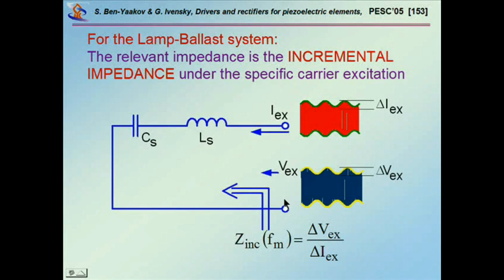And as it turns out, you can do it by simply converting this circuit to two parts, with a technique that we call envelope simulation. By doing this, you get rid of this carrier and you are just dealing with this envelope. This is very effective because simulation, of course, is very fast.